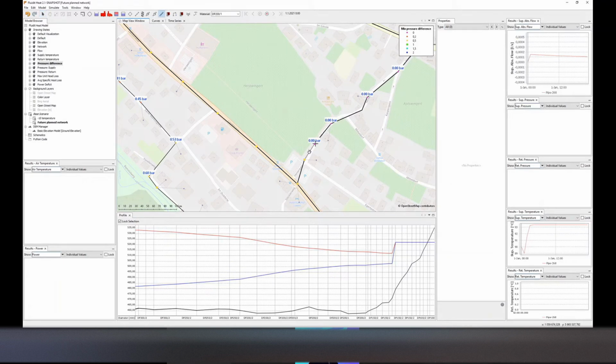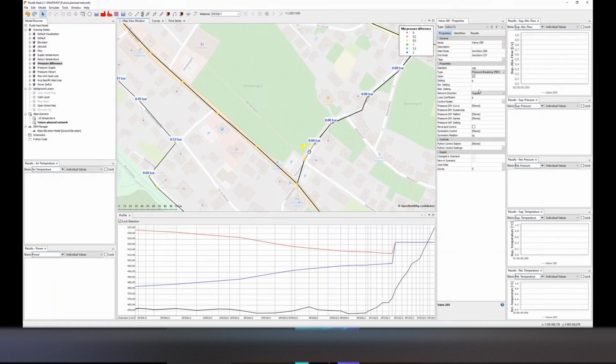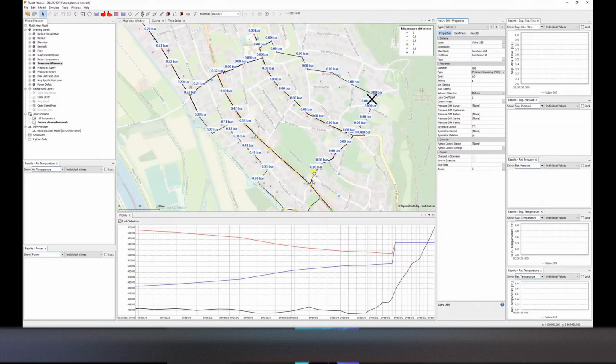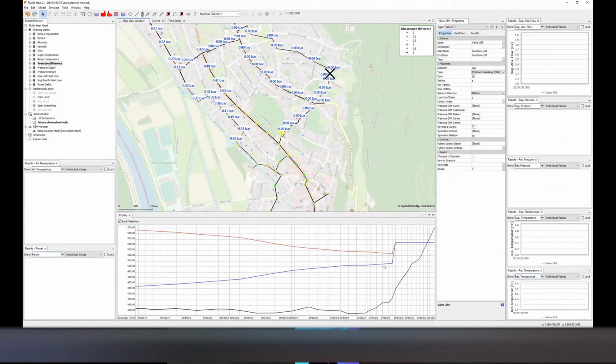And then I have to create a valve so that the return water can find its way back here. And I will, sorry, not loss coefficient, but I will keep 4 bars of pressure braking. So if we look at this profile, now that I have created the valve also, and the pump will be keeping 1.5 bars of pressure difference here.